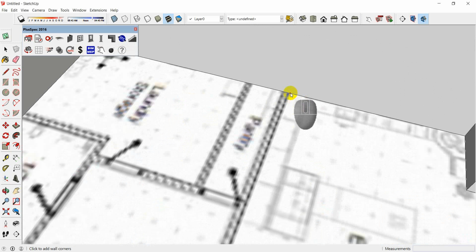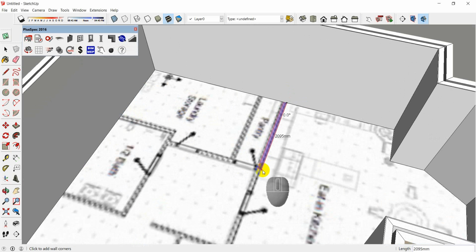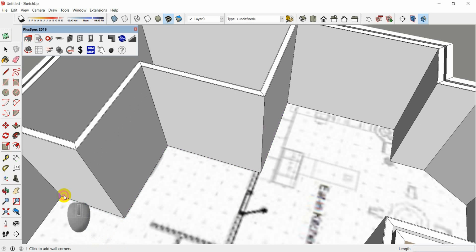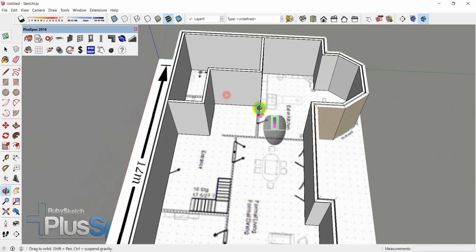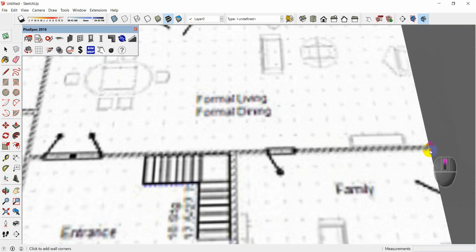And I'm just going to quickly do a couple of walls here. So I'll go from here to here, say, here to here. Now you might have different types of linings in powder rooms and so on. You can change those as well in those menus that I showed you before. Okay, and so I go from, say, here to here. Right arrow or insert will get you out of that, so you can change where you want your wall to go.